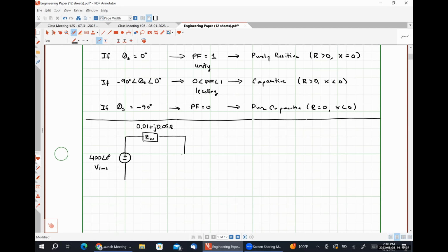And then we're going to have another impedance here, and I'm going to call this Z sub M. It's going to represent the impedance of a motor. So practically all electric motors also represent inductive loads. In fact, you can generally say that if it moves and it runs on AC electricity, it's going to show up as an inductive load. The characteristic impedance of 8 plus J2